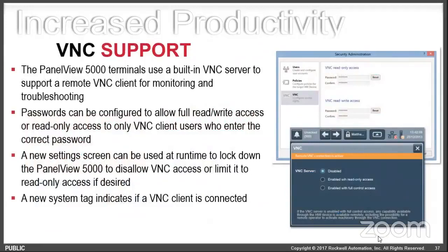VNC support. We talked a little bit about that for the PanelView Plus 7, and this works the same way, where there's a VNC server built in, you can turn it on, and you can set the read-only access, write-only access, all that security stuff, because you don't want just anybody going in there and seeing what's going on or making changes. There's also a tie-in with ThinManager, where you can see that content and mirror that content through ThinManager. Michael will be talking about that a little bit later on.